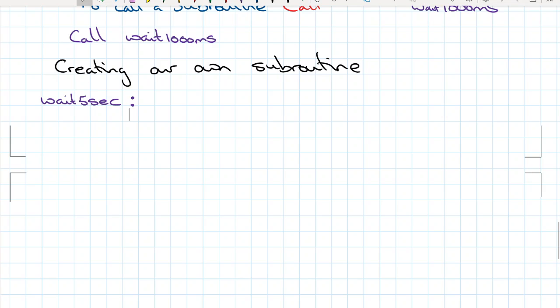The first thing that we need to do is to save the working register when we enter a subroutine. The reason why we do this is that working registers get used within programs, so we need to keep it nice and safe and then restore it once we've finished, and it just keeps everything ticking away quite nicely. Sometimes you can equate the working register to a name, so you quite often see in some of these codes wsave. I'm not going to use that, I'm just going to put it into a register rather than equate a register to a name.